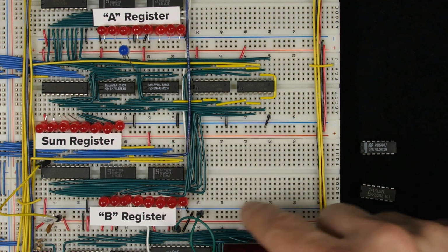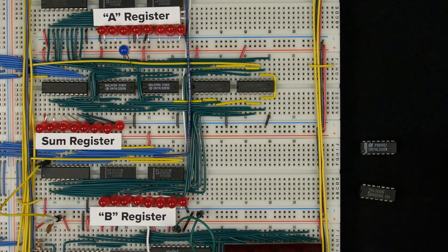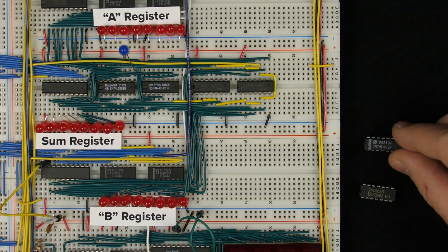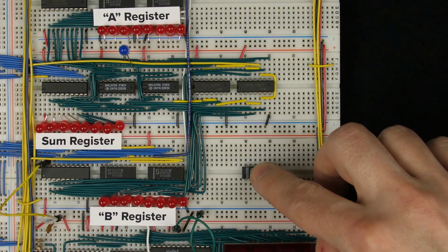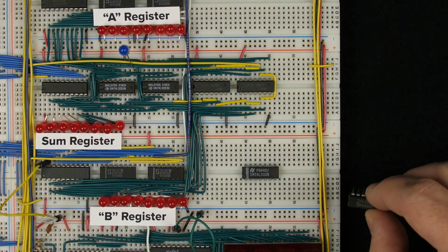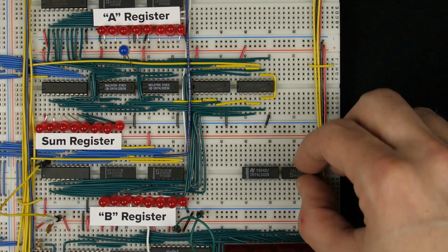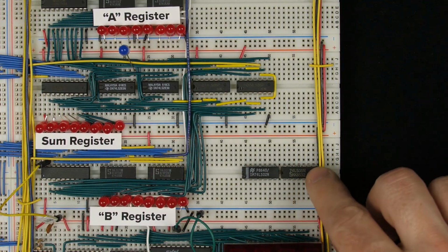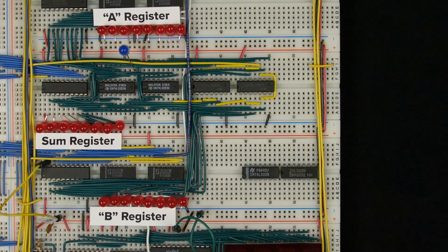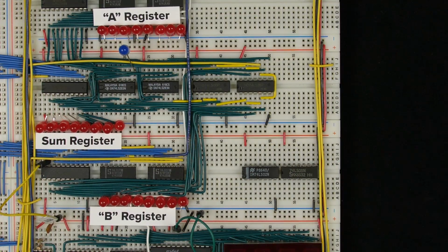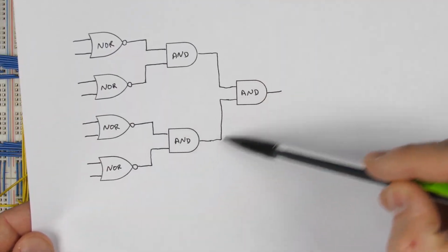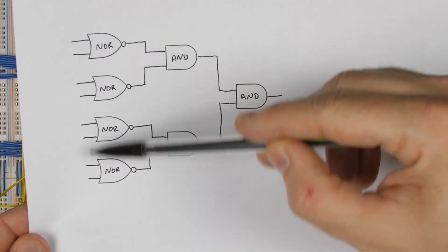So I'll build up that 0 evaluating circuit over here in some space that's free near the ALU. So this is the 74LS02 with the 4 NOR gates that we'll use to NOR each pair of bits. And this is the 74LS08 with the 4 AND gates that we'll use to combine those. And of course, we'll just use 3 of those AND gates. Like any of these other chips, I'll hook up power and ground to each of them. So I'll start by connecting the logic between the gates before I worry about hooking up the 8 inputs.